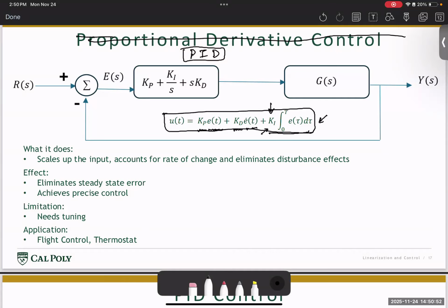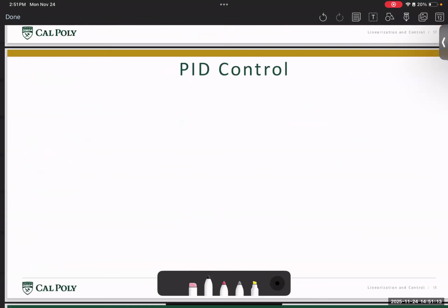for specific controls like a quadcopter or the attitude control of the spacecraft, there's enough study that's done that gives you some amount of direction for tuning the controller. So tuning doesn't really become a big problem, and we eliminate the complete steady state error, or in other terms, we achieve precise control. So this is the type of controller that's usually preferred.